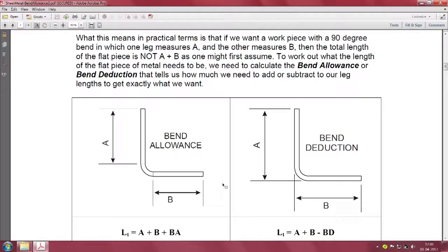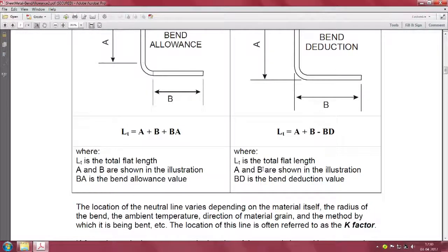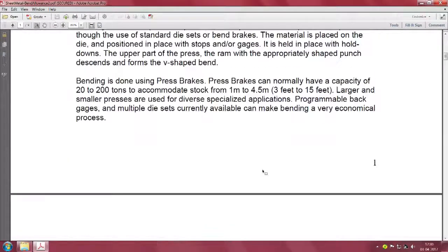The difference there is all about the K factor, saying how do you determine the K factor, and the words scientific and trial and error are used. Instead, here this is more related to if you take the internal dimensions minus the bending radius, how do you add a bending allowance, or in the case you want to take the external dimensions, add the external dimensions and then remove the internal dimensions. So, once again I will read this first part of it.